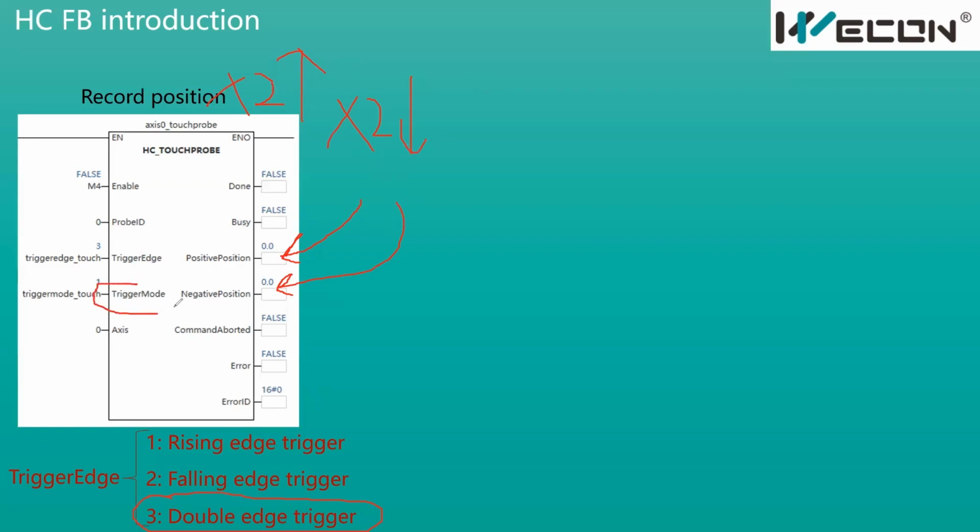And for this trigger mode, we have 2 modes, 0 and 1. 0 means our touch probe will only record 1 time. After recording 1 time, it will change to done status, so this function block will not take effect anymore.